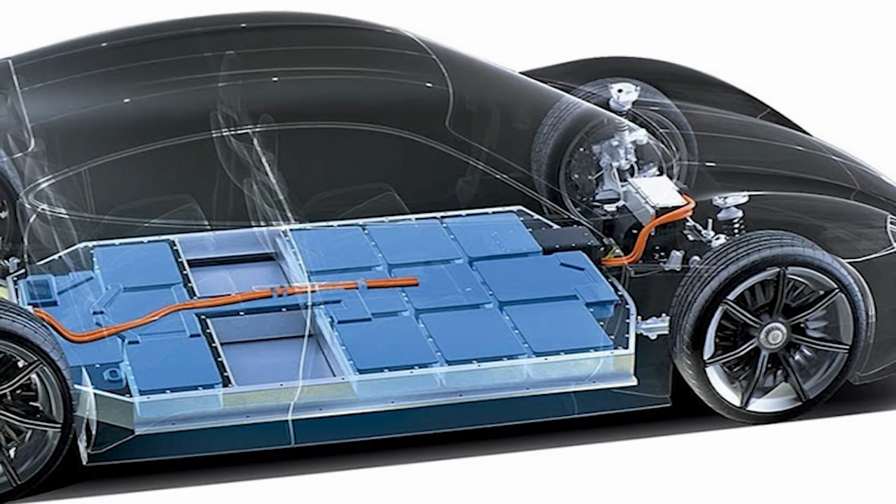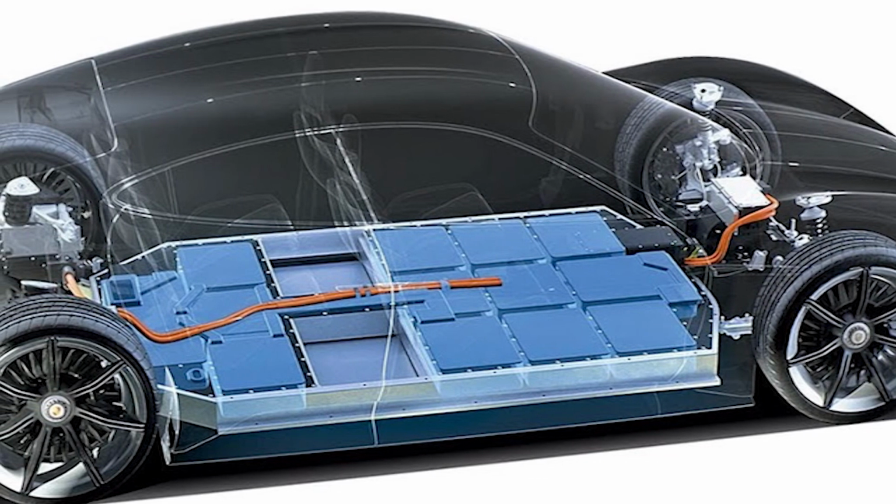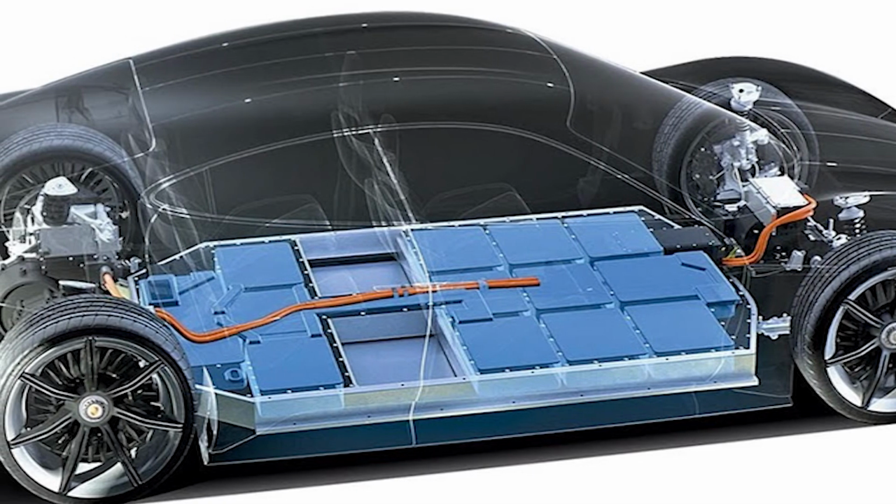Basically the heat sink design itself is a different concept, where we need to study the power rating of the converter or the inverter, the amount of current flowing into the system, the maximum temperature produced, the maximum heat being dissipated, along with what amount of area is available in the vehicle, and what is the volume of the heat sink that is required.